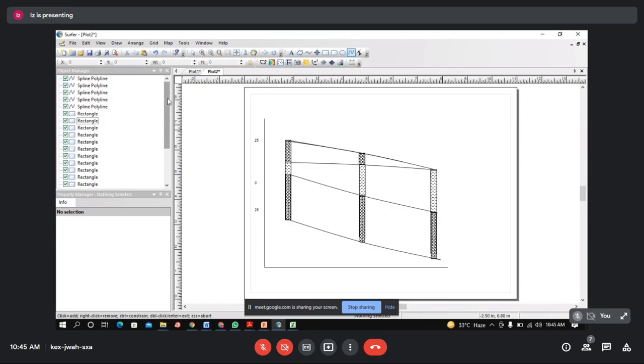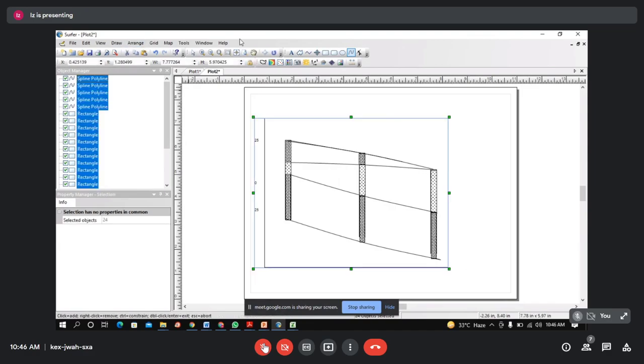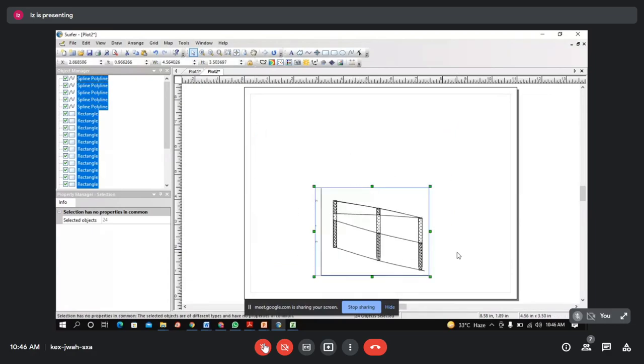And if you have multiple wells, that means you have sufficient wells sufficiently covering the area, you will have the data to construct a 3D geological model of your area. Okay, we call this cross sectional image a hydrogeological cross section. And if you include multiple wells, if you include more wells into this current setup, I'll show you.